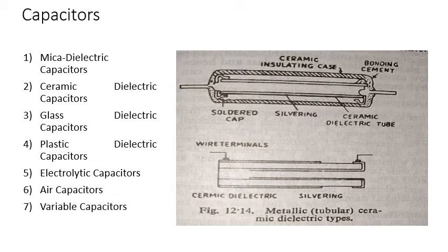So this is the electrolytic capacitor, and non-polarized electrolytic capacitors are also available for application in AC circuits without any DC polarizing voltage. A non-polar capacitor actually contains two capacitors connected in series with opposing polarities.